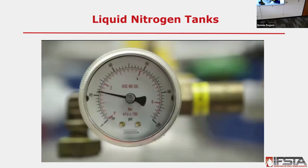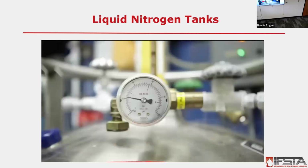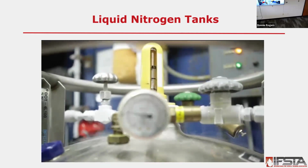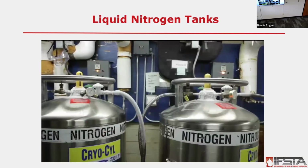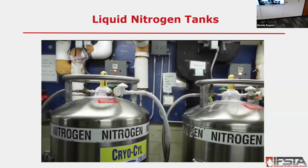The primary and secondary pressure relief valves on this tank are set at approximately 20 psi and 50 psi. Other liquid nitrogen tanks may be rated for higher pressure settings, so be aware of the specifications for your tank. Do not remove or tamper with any of these safety devices or their protective covers.